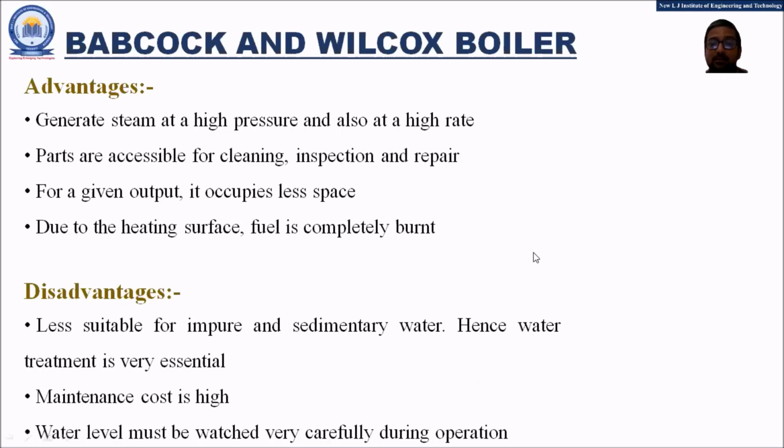Now let us understand some of the advantages and disadvantages. It is used for generating steam at high pressure. The parts are accessible for cleaning. It gives a given output in less space. Fuel is completely burned. Some of the disadvantages: it is less suitable for impure and sedimentary water. Water treatment is essential. Maintenance cost is higher and careful attention is required for the water level.